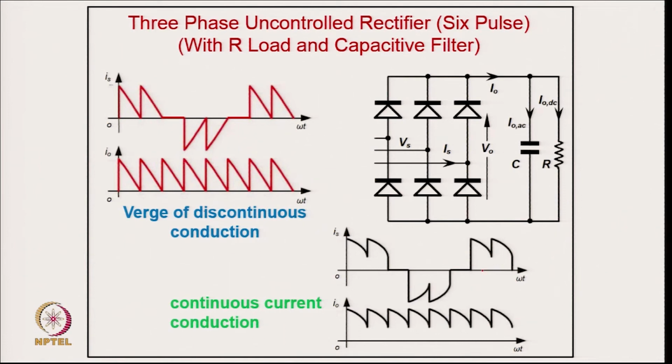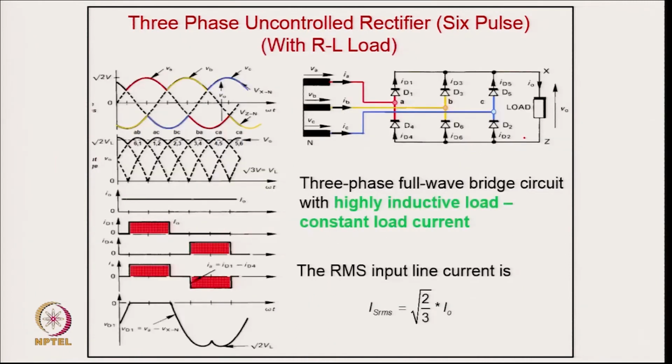We will discuss many problems of such nature. So it draws quite a large amount of harmonics, even the THD may be like 60 to 65% or so, depending on the load nature also. And then this is a typical example. If you have a highly inductive load, then you will be drawing typically this kind of quasi-square wave supply current. So it has harmonics, of course, not the reactive power burden because it is an uncontrolled one.